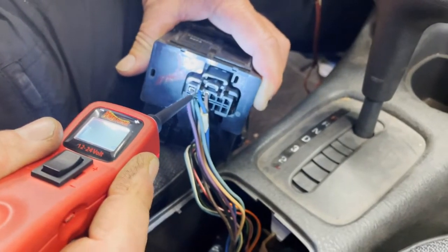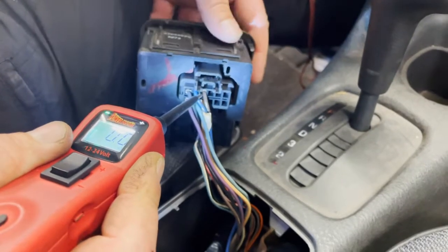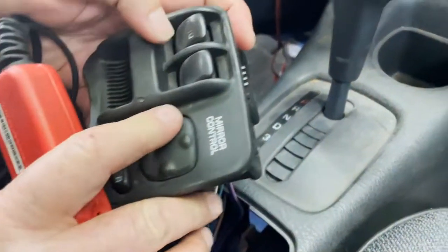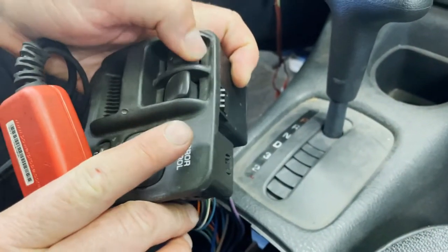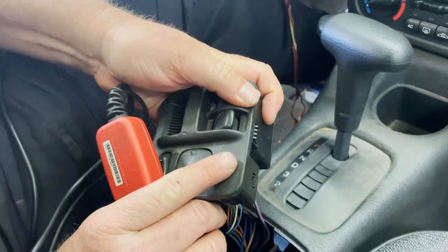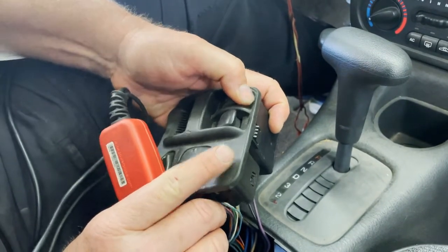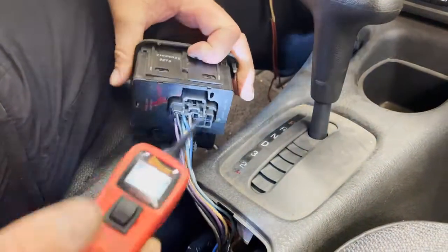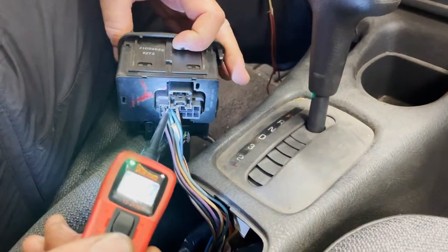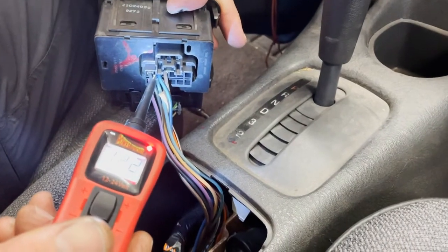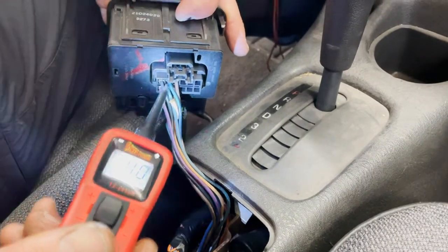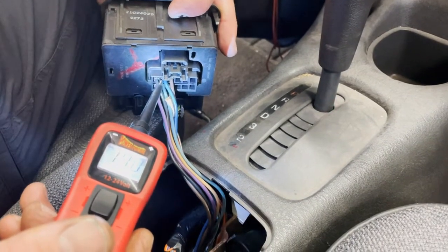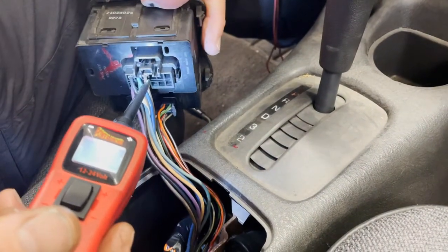So what happens is you go to 1, you hit the window switch. So let's find this is the switch for the driver's door. Okay, it works. All right, so now I'm going to go to the blue wire, and I'm going to go up. And you see that it sends power from the purple wire to the blue wire when I hit up. The dark blue wire,